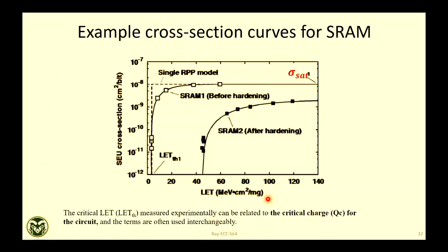Okay, so this is a typical way of measuring this soft error rate. When you test a chip, you basically plot these kinds of things. You find out what the critical LET is. For example, if you have a rad-hard process, you should have a critical LET, meaning the LET at which you see failure is happening. That means critical charge condition is achieved, right? And then there is some probability it will saturate after some time, but there is a range. So you can say what the critical LET is and what your critical cross-section is. These are the two important ones. So what is the saturated cross-section, sigma SET, and critical LET. These are the two important parameters to quantify soft error or single event upset.